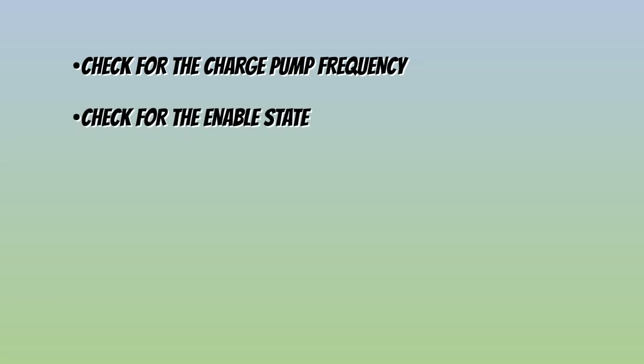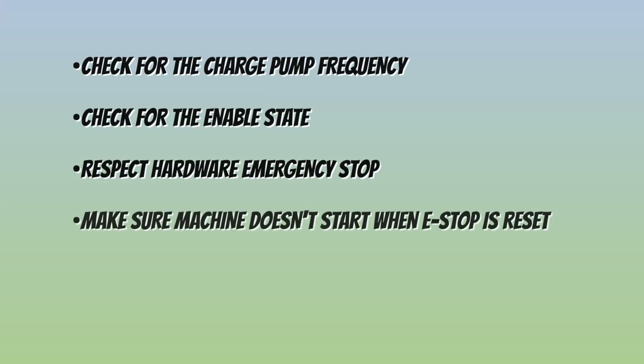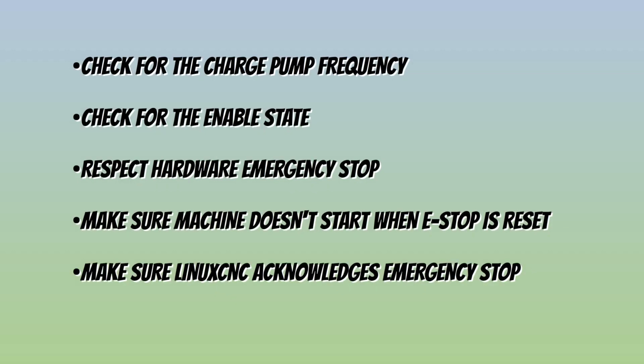We need a way to check that LinuxCNC wants the motors to be enabled. We need a way to respect the hardware emergency stop and report it to LinuxCNC. We need a way to make sure that when we release the emergency stop, the machine doesn't start up again. And ideally, we also need a way to check that LinuxCNC has acknowledged our emergency stop.